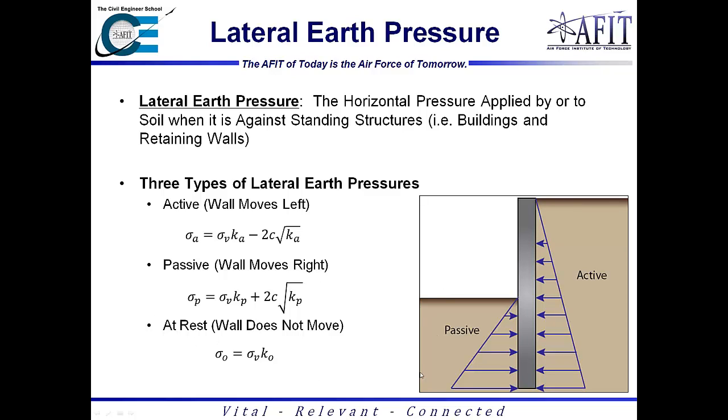But then you have something called at-rest pressure. So if you have something that you're fairly certain will not move, i.e. a foundation of a building or a basement wall or something like that, you could use what they call at-rest pressure and just assume it won't move. However, with retaining structures such as this, you have to consider active and passive stresses.